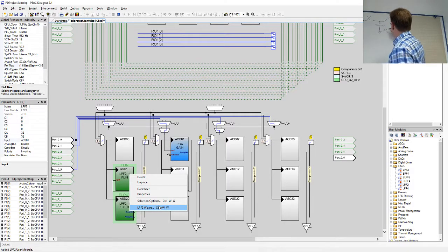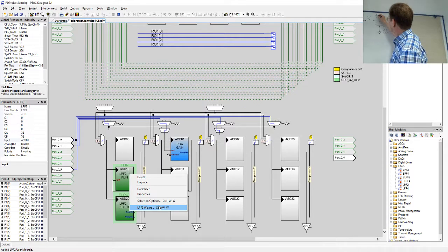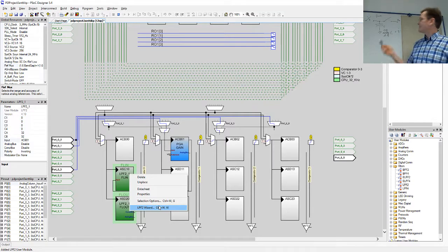But anyways, so you basically transfer a charge at the rate of some clock frequency, meaning that actually you're not doing dq or dt times capacitance equals current, directly proportional to the switching frequency, which means, okay, this is actually a resistor.